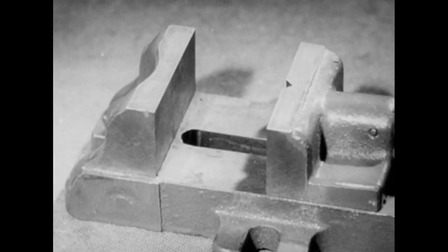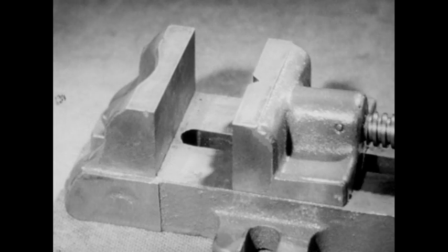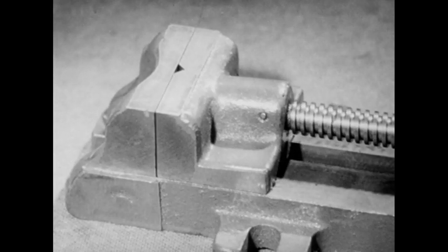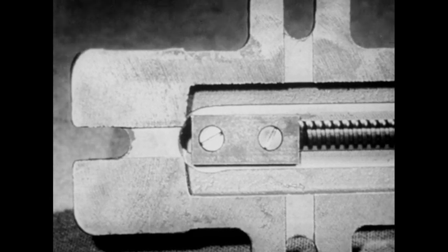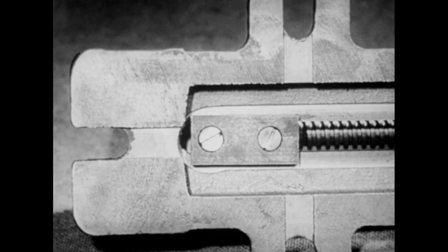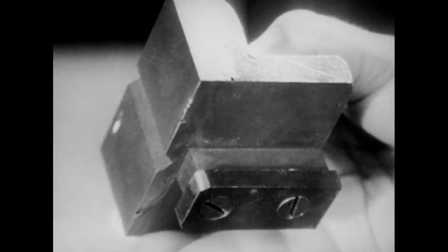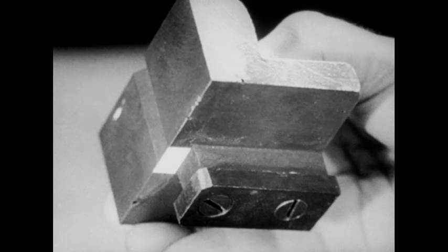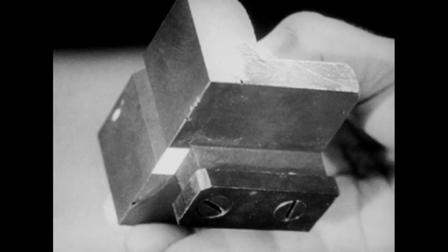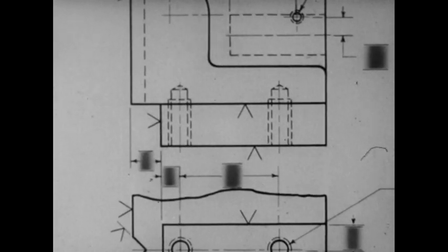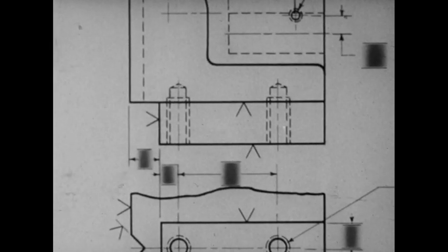So that the jaws come together, the length of the tongue must be less than the length of the movable jaw. Otherwise, the tongue would hit the round end of the slot, which results from an end milling operation. Since this end of the tongue will be cut off by a machinist, you should provide a dimension to show the size cut he must make. Give this dimension, which establishes the length of the tongue on the side view.